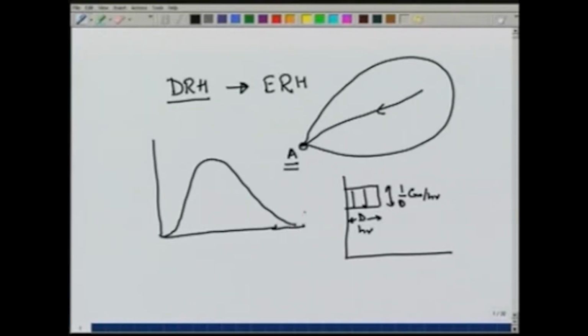And it would look like this, where the time may be in hours, and the stream flow is generally in meter cube per second. The use of the unit hydrograph is to estimate the runoff for any rainfall. For example, we can easily estimate the rainfall which is likely to occur once in 100 years, and based on that pattern of rainfall, we can apply the unit hydrograph and estimate the runoff for that once in 100 year rainfall, and we can use that to design flood control structures.